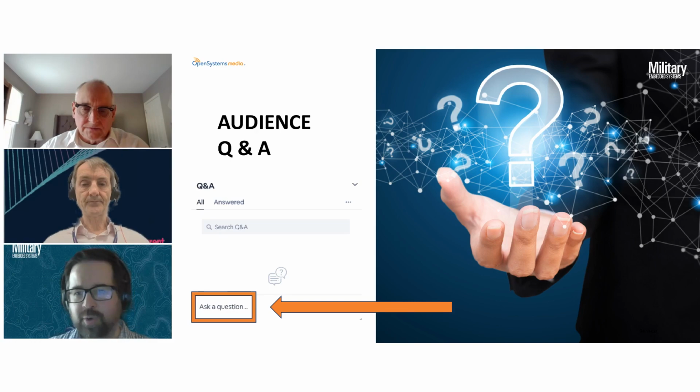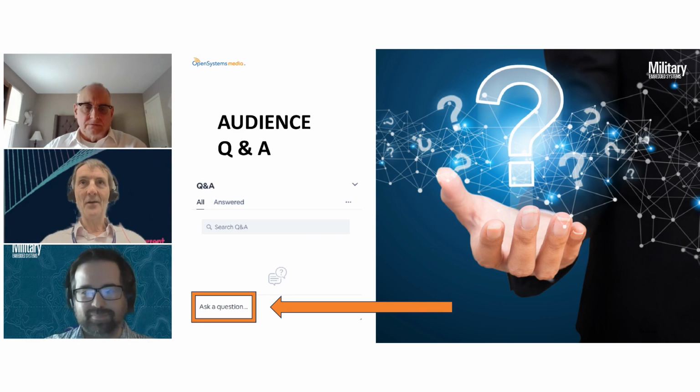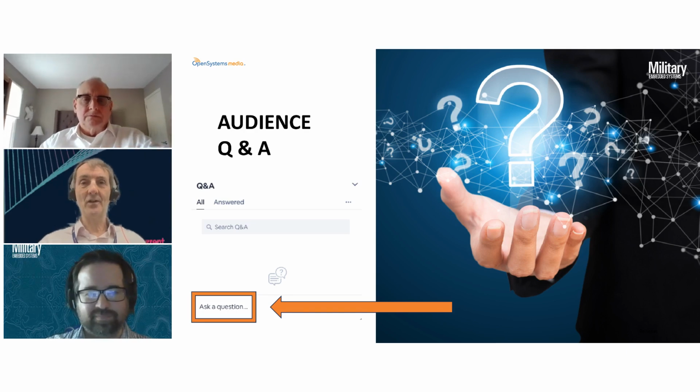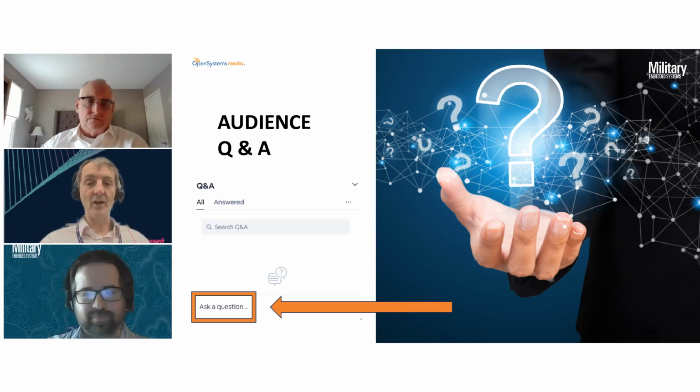Okay, great. I think we have time for one more question. So Nigel, I'll leave it with you. Technology transitions sound good in principle, but are they really practical? Yeah, let me give you a really good use case. We have an existing customer who took a small handful of one of our early SOSA aligned compute intense profile boards to do their initial development work. They were happy with that product, but it didn't meet their weight constraints, nor the upper temperature limit they needed for their system. The original card was plus 70 degrees C max card edge. They wanted an 85 degrees C card edge implementation.